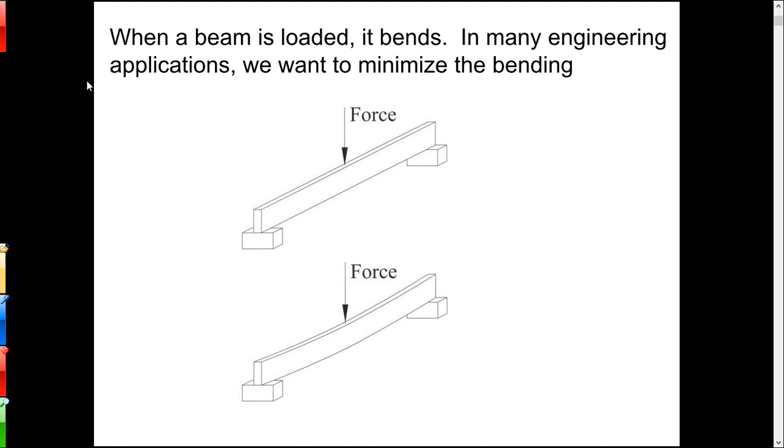Whereas with the mass moment of inertia, you don't just look at the area, you consider the mass of an object. And what you get from the mass moment of inertia is the tendency of this object to resist angular acceleration when you apply a moment to it, okay? So they're different, they're calculated in very similar ways, but they describe slightly different properties, okay?